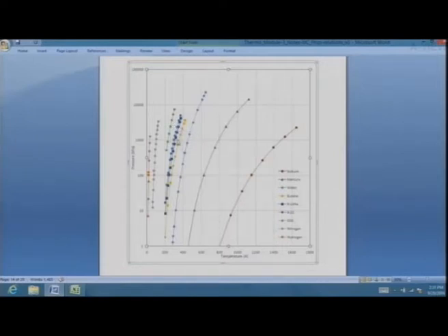one another. They are R22, R134A, these are hydrofluorocarbons of different types. And then this one, which is butane. The reason for bringing butane and all these substances together is that if you look at the thermodynamic properties of all these, they are somewhat comparable. And so one would say that I could have used butane as a refrigerant, or better still, substitute the hydrogen in butane or propane or ethane by chlorine or fluorine, and you start getting all these wonderful chemicals which were the refrigerants. And it was these wonderful chemicals that were responsible for ozone layer depletion.